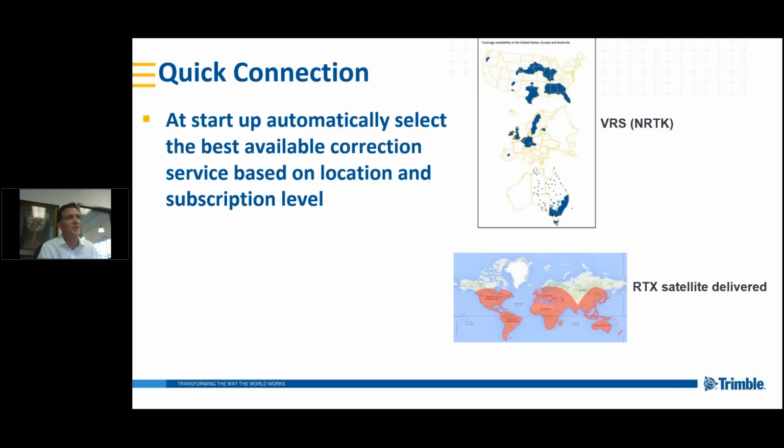You may be interested to know that the fastest growing customer base that we have, and I know Topcon has as well, for RTK surveying or network RTK, is the farmers. So high-tech farming. They're using an RTX-delivered correction only in some cases, because they don't need fast initialization time. They don't care about 10 minutes in the morning to get an initialization, because they're not jumping in and out of the truck all the time, and they also don't worry about losing lock, because that 10 minutes starts over again, since they're in the open field all day long. So they're using, in some cases, RTX only now.